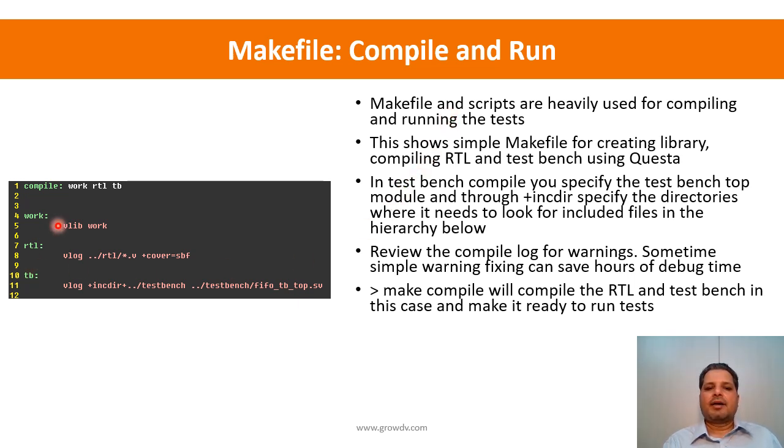So now let's look at how we compile this type of test bench. I'm showing it with QuestaSim, but the same concepts apply even if you do it with either VCS or the Cadence tools. For any of the tools, the concepts remain more or less the same.